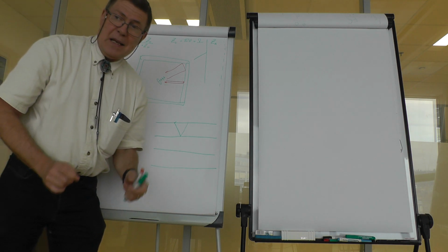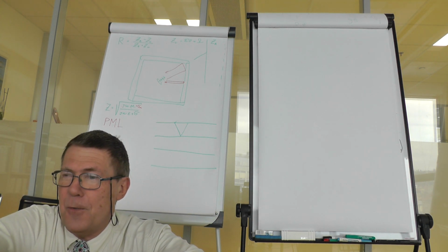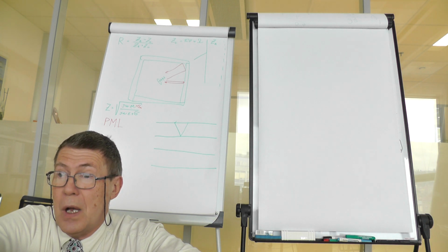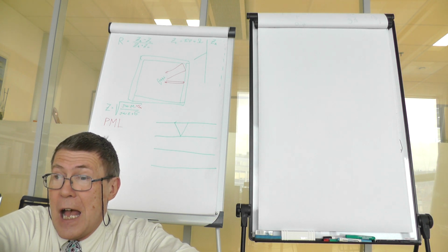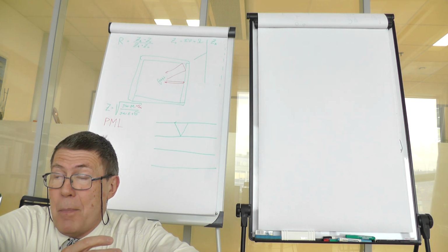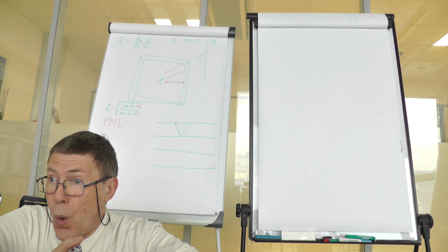So this is an important idea that is used in finite difference time domain calculations in the case that you should simulate an open problem. By open, I mean a problem that is not closed within magnetic or electric walls.